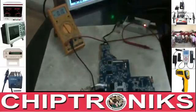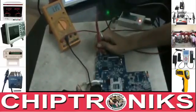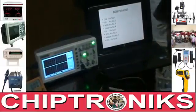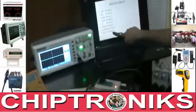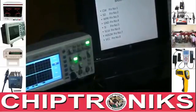Now you need to check pin number 7 also. It has the same voltage, 3.3 volts. Yes, 3.3 volts. And you need to check pin number 3, the write protect pin. Here also we need 3.3 volts. If you do not receive this voltage on pin number 8, the VCC pin, then your BIOS IC is not working, and your laptop motherboard is in dead condition. That's why these 3 voltages are required on the BIOS legs: pin number 3, pin number 7 and pin number 8. They are necessary, otherwise it will not work.